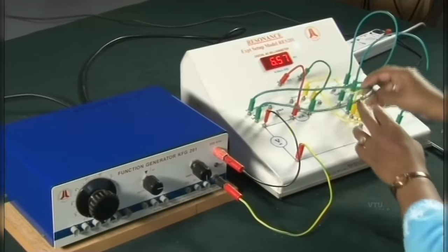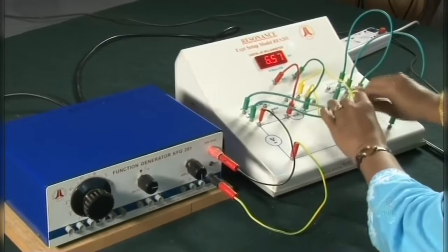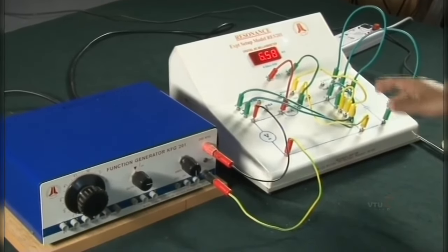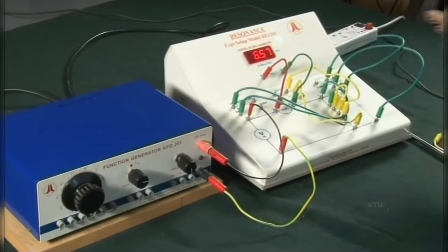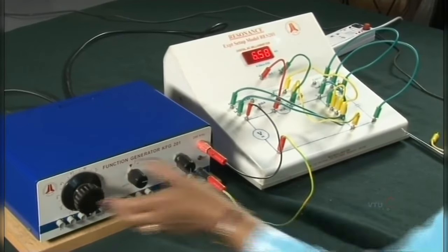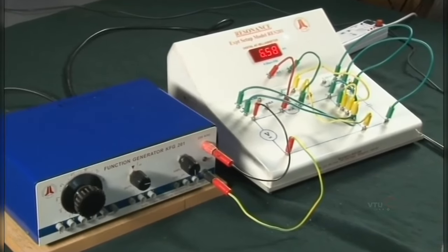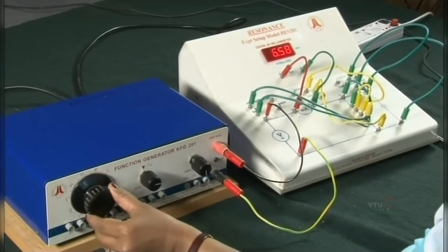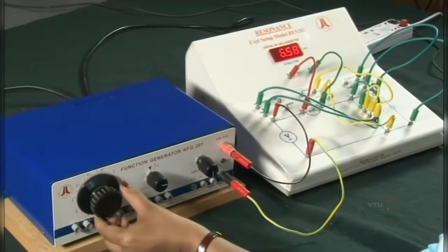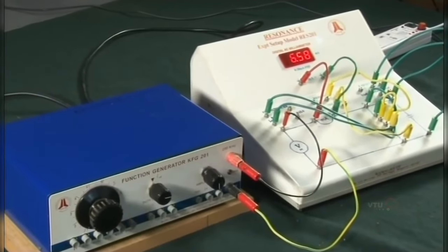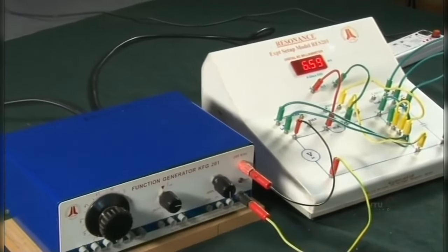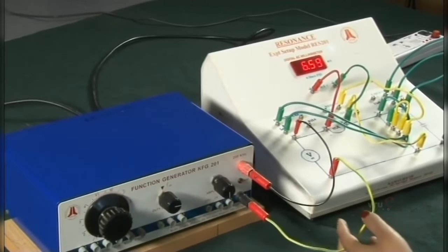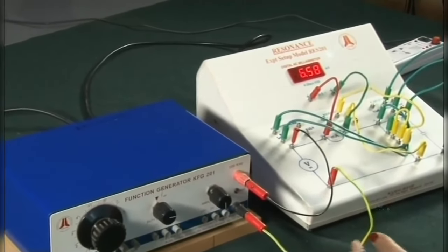We repeat the experiment in the same steps because the resonant frequency of the circuit is the same, as we have not changed the values of L and C. So, the circuit resonates at the same frequency, but the current through the circuit, you observe, is maximum initially. At 1 kilohertz, the initial value of applied frequency, you see that the current is showing maximum.